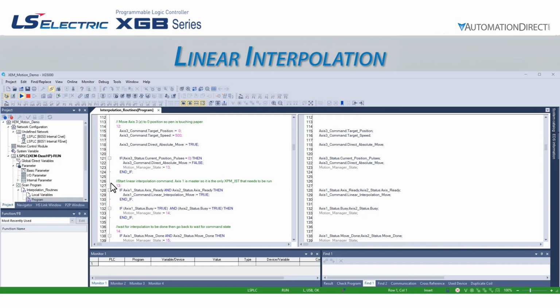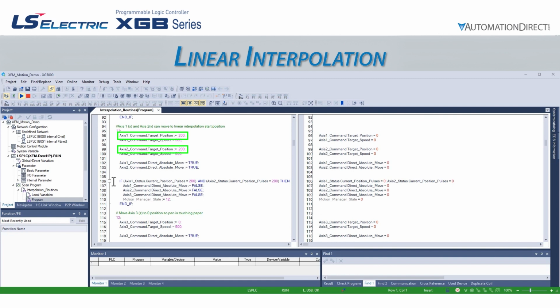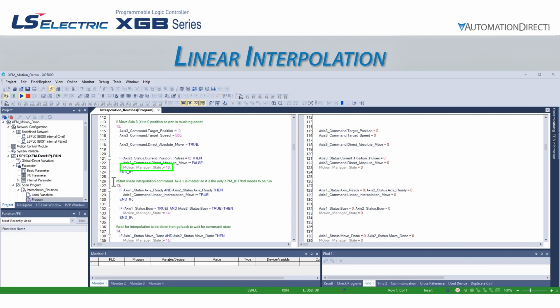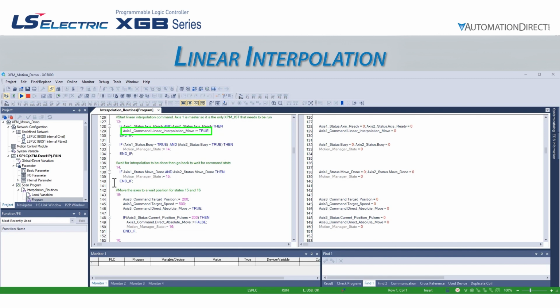The z-axis in this case is positioned so that the pen is touching the paper, and the x and y axes are both positioned at 200 pulses. The final function in motion state 12 is to move to state 13, which is the actual execution of the linear interpolation. We see in state 13 that it will make Axis1Command.LinearInterpolationMove true.